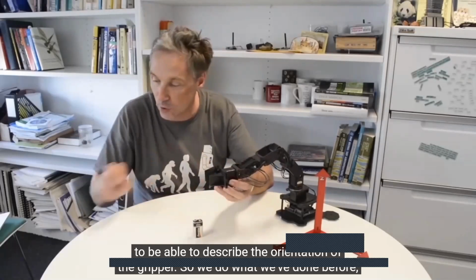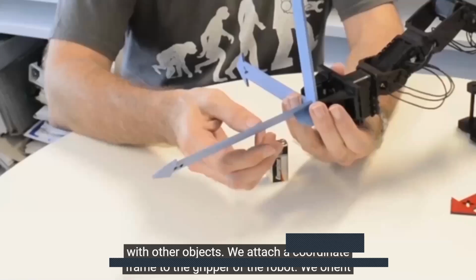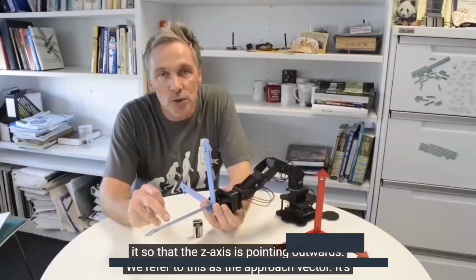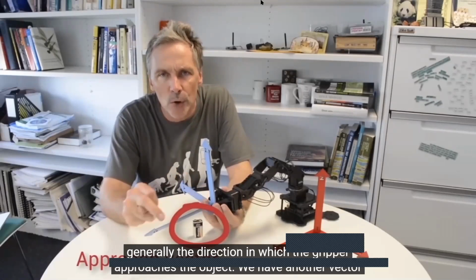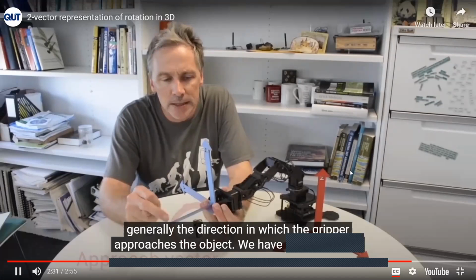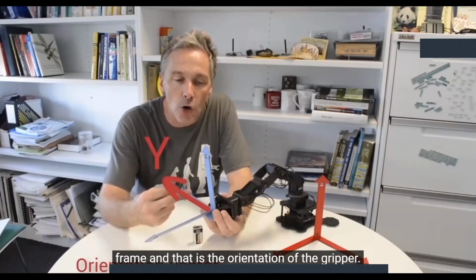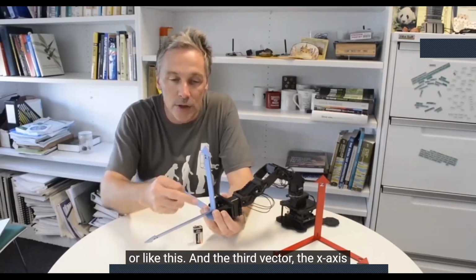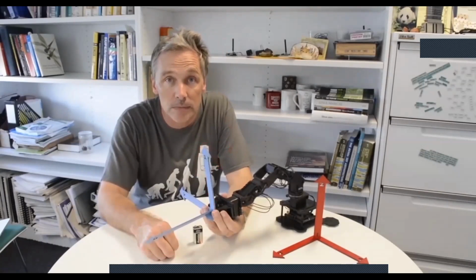So we do what we've done before with other objects. We attach a coordinate frame to the gripper of the robot, and we orient it so that the z-axis is pointing outwards. We refer to this as the approach vector. It's generally the direction in which the gripper approaches the object. We have another vector which we call the orientation vector, and it's parallel to the y-axis of the gripper's coordinate frame, and that is the orientation of the gripper. Do we want the gripper fingers like this or like this? And the third vector, the x-axis, we refer to as the normal vector.